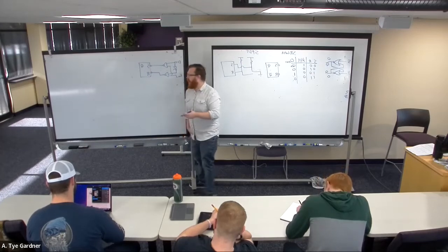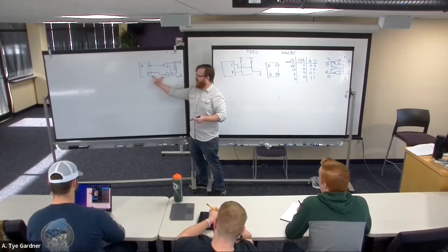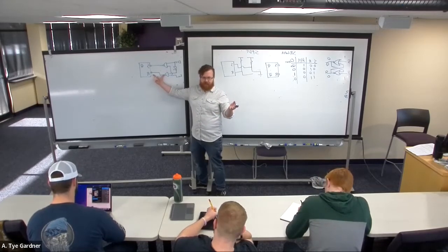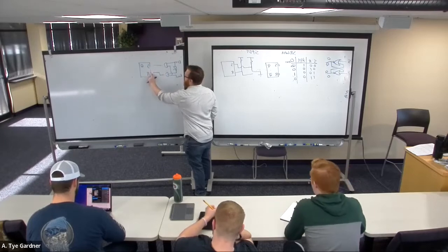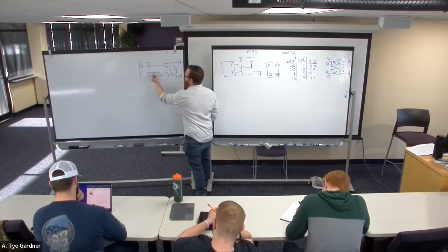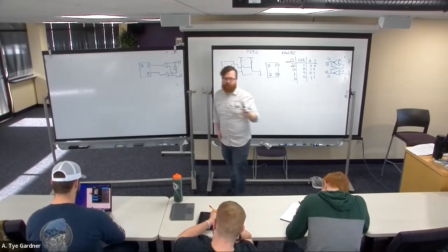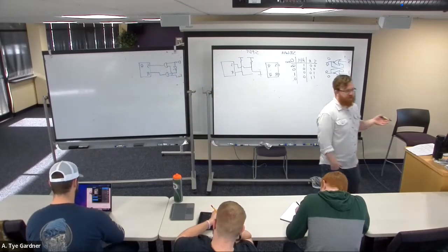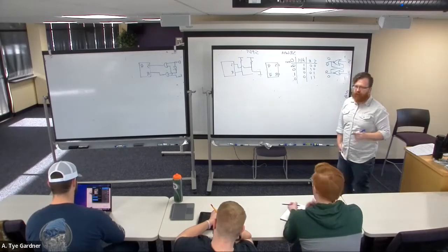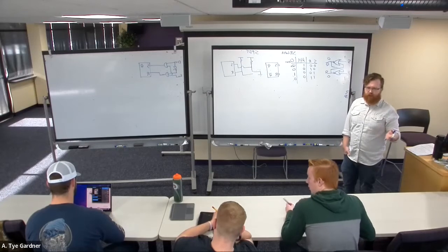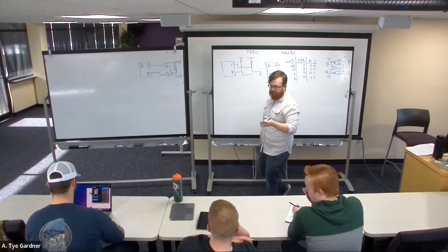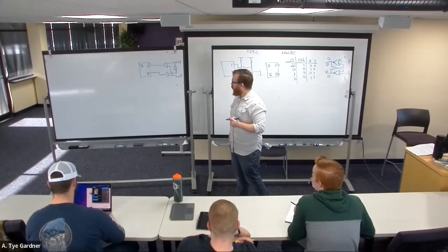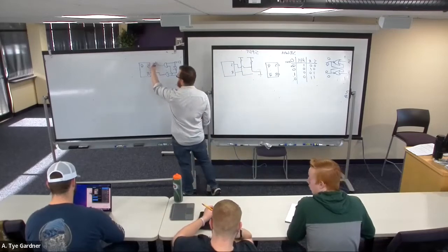So if I want to start with that, then I can just cancel out these bubbles, right? I can know that inside they're all NAND gates, but I'm going to simplify the drawing because it makes it just a little bit easier to talk about. So cancel the two inversion bubbles. And I have AND gates, which are really easiest for us to talk about. What does an AND gate do, right? But it doesn't change the functionality. We understand that it's still universal gates. I've just drawn an equivalent circuit. So the first thing that we'll notice is if EN, enable, is 0, what does that do to these signals that I'm going to call A and B?